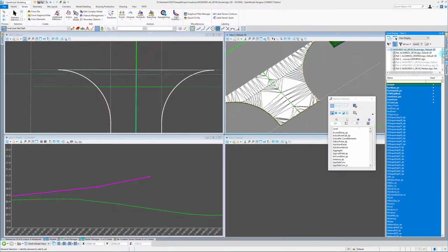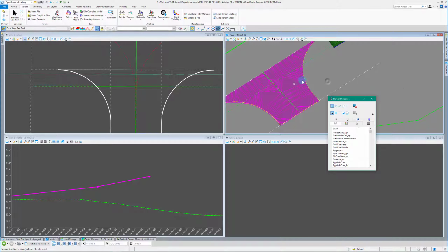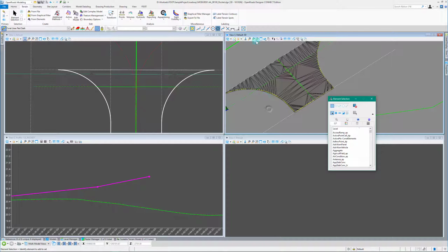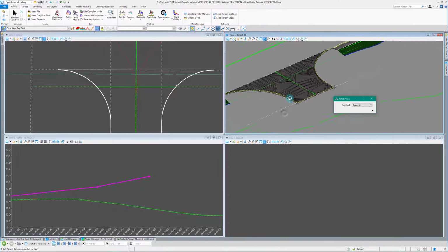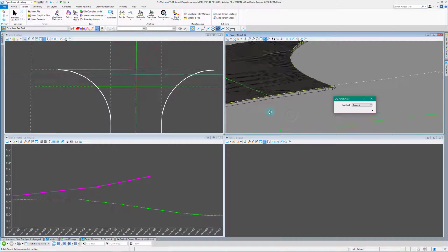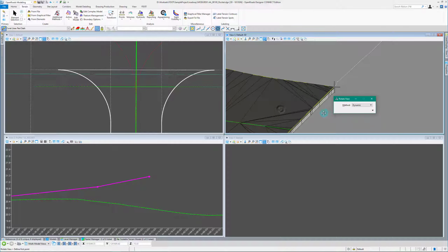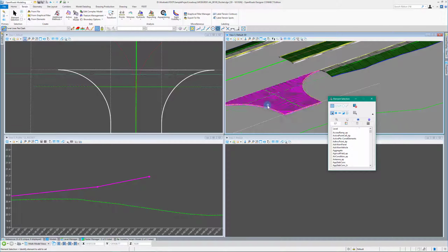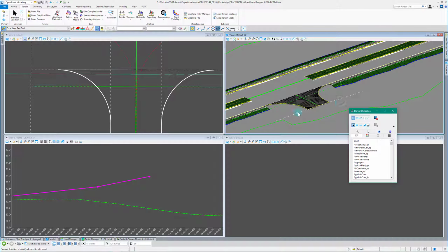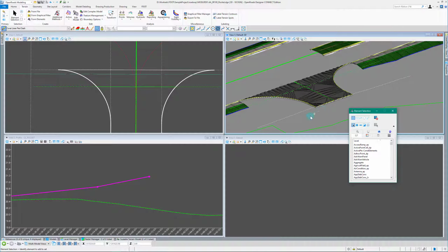and I turned it off in here, it looks like. DTM top mesh was kind of covering it up. So now that we've turned that DTM top mesh off, you can see we have our pavement surface. So the next thing we're going to do here is work on our corridors for our curb returns.